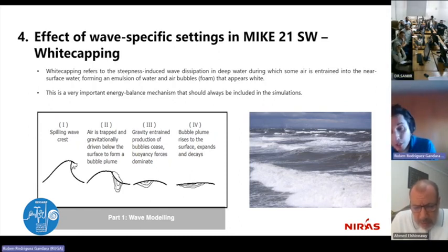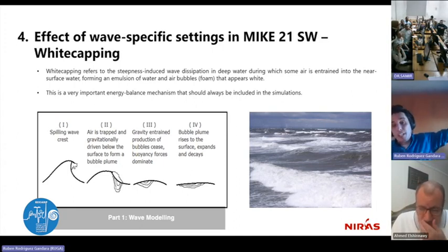So your model results will not look like reality, because we know that waves break offshore due to white capping. The bottom line, don't forget to include white capping.